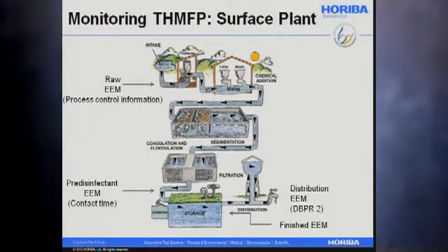So in terms of a typical surface water treatment plant, again, the surface water can undergo very drastic variations in DOM concentration depending on snow melts, floods, seasonal periodic droughts and things that cause different concentrations. So knowing the concentration of these dissolved organic matters from the outset is very important in terms of process control monitoring for controlling the coagulants and the other polymers and things that get added to the raw surface water before it enters the coagulation and flocculation tanks and sediments out and then gets filtered.